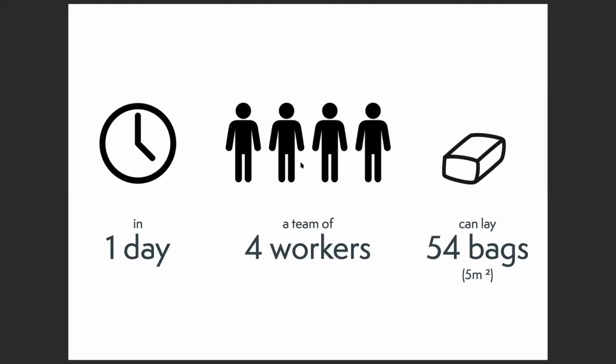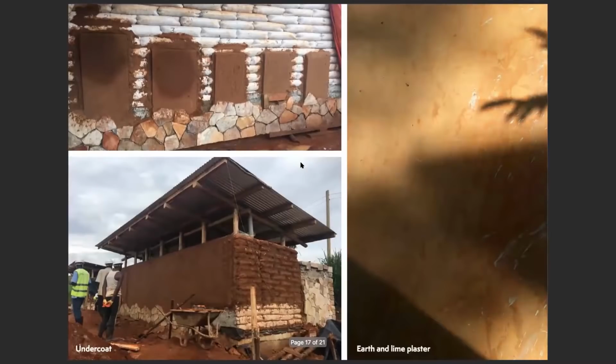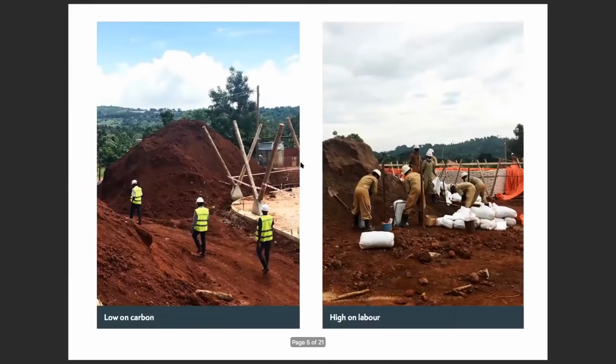Well, I thought I wasn't going to talk about the structural design, but yes, the walls not touching the roof means they are working more like fence walls or perimeter walls that have no proper bracing. Of course, the roof always holds the walls together, and that would structurally have been a much easier and more comfortable thing to do: the roof holds the walls together, and the walls easily hold the roof together.